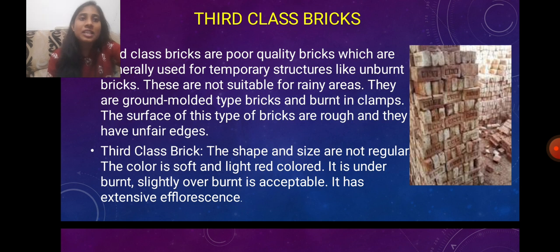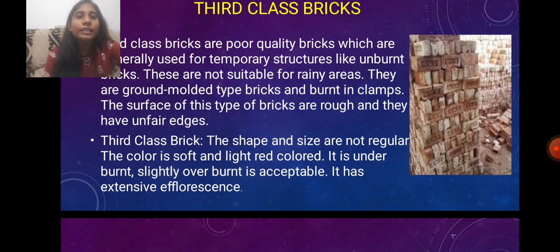As compared to first class and second class bricks, third class bricks have a very rough surface, light reddish color and uneven shapes and color, and they are overly burnt. Lightly burnt can be acceptable, but overly burnt bricks cannot be accepted, so they are used in places like foundations and somewhere else.